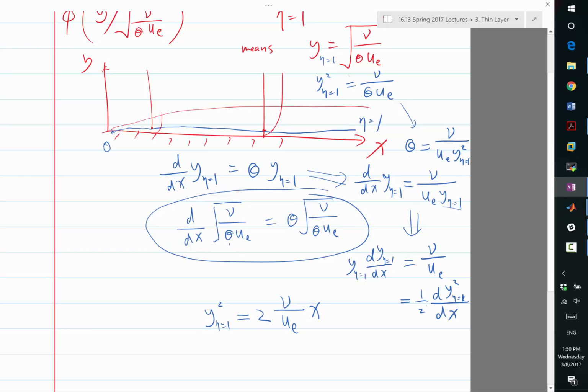Yeah, so here we are assuming the leading edge started with x equal to 0. Right. So then we are defining x to be the location on the flat plate relative to the leading edge, where the thickness of the boundary layer is 0. Okay, and you can look at this equation and this definition, this equation where we got theta.